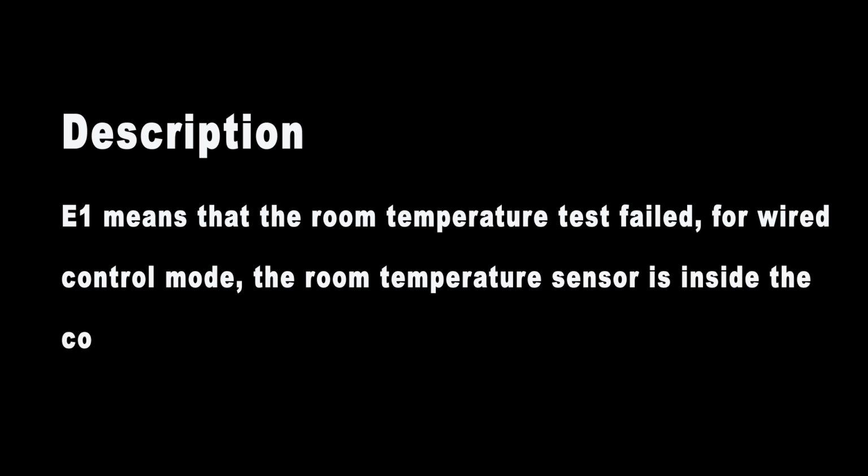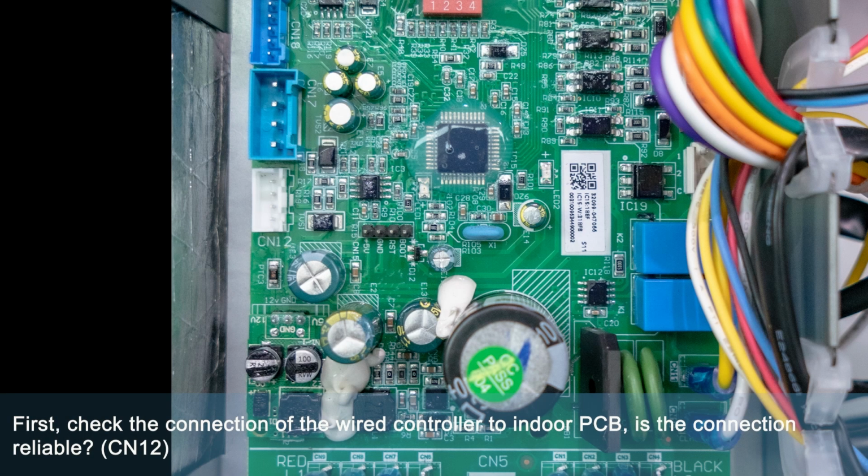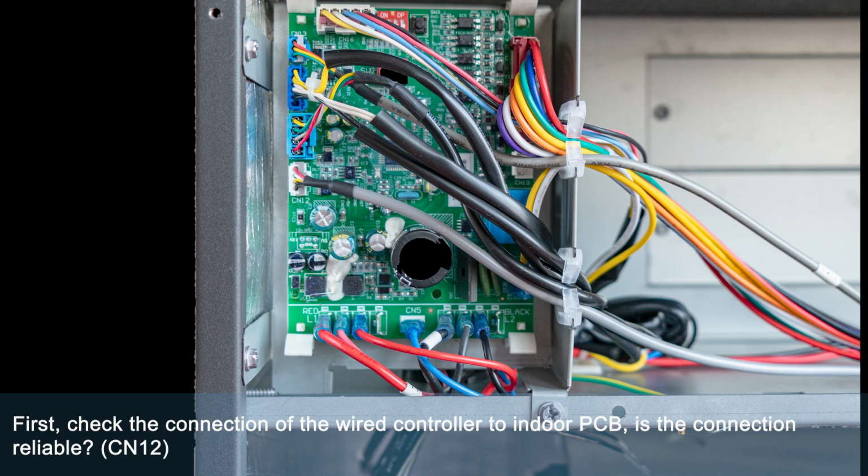E1 means that the room temperature test failed. For wired control mode, the room temperature sensor is inside the controller, as shown in the photo. First, check the connection of the wired controller to the indoor PCB. Is the connection reliable?